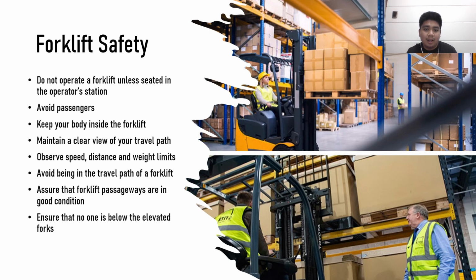Ninth, aisles and passageways shall be kept clear and in good repair, with no obstruction across or in aisles that could create a hazard. And lastly, never allow anyone to walk or stand under the elevated forks, even if the forks are not carrying a load.